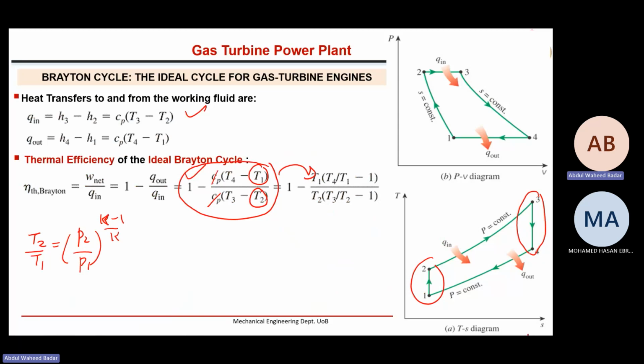We never used this equation in the previous chapter because it was not an ideal gas. And also Cp, we were not assuming constant. We were taking actual values from the table or chart. So the Cp as a function of temperature effect was there. But here I'm saying constant Cp, isentropic, and the third thing, ideal gas.